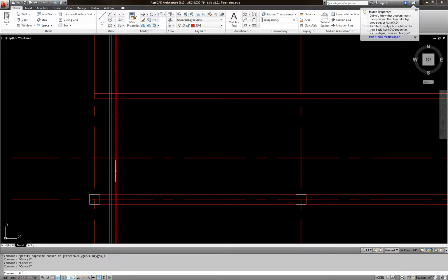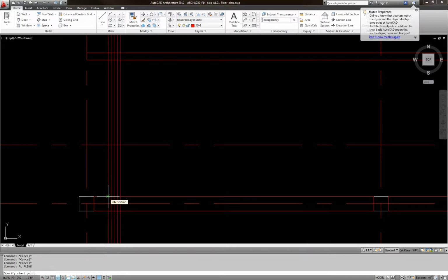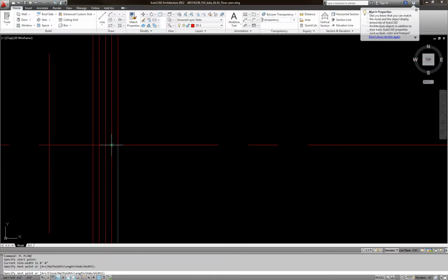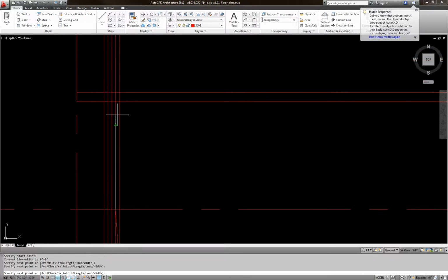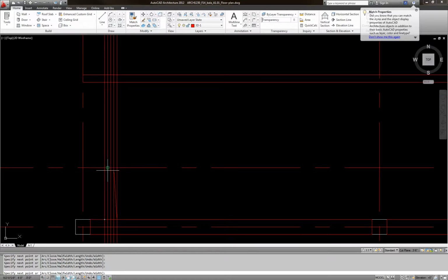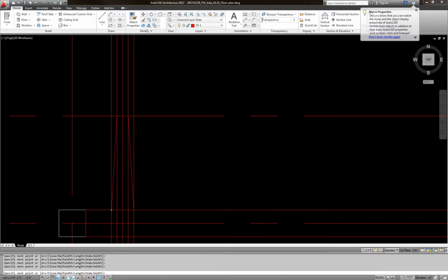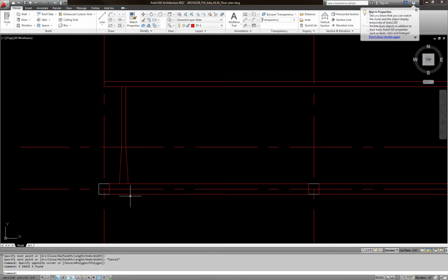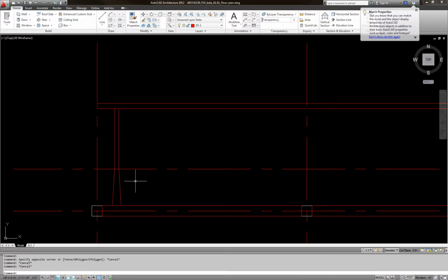I'm going to do polyline, PL enter. I'm going to click on this point, go to that point. I'm going to go to the second line here, and I'm going to go straight, and I will go to the third line, and I'm going to come down here. I'll go to the last line, then I will restore this. So this is my, remember I told you